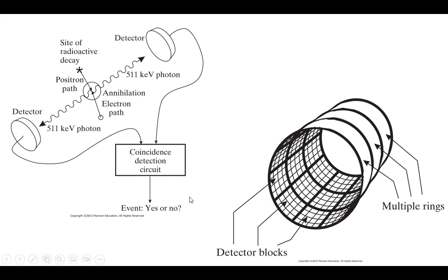And away we go. Then we have to check, is it coincidence? There are two types of these coincidence detectors. I can set a time window. This is option one, the easiest one. I just say anything that happens in 250 nanoseconds, if it happens inside that window, I call it good. I'm not neglecting anything. Maybe it's 100 nanoseconds, whatever window you pick.